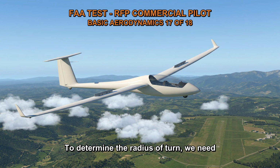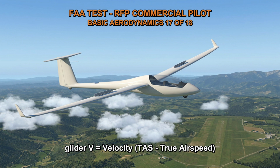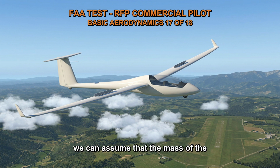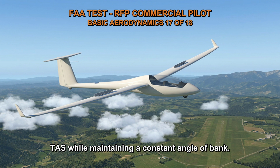The correct answer is C. To determine the radius of turn, we need to consider the centripetal force acting on the glider. Centripetal force is given by the equation F equals m v squared over r, where F equals centripetal force, m equals mass of the glider, v equals velocity, TAS, true airspeed, and r equals radius of turn. In this case, we can assume that the mass of the glider remains constant, and we are changing the TAS while maintaining a constant angle of bank.